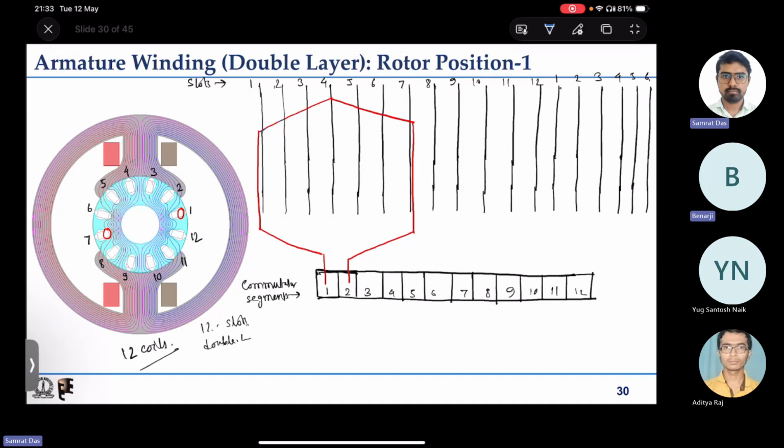So unless one is at the top and the other at the bottom, if you want to keep both on the top or both on the bottom, then the overhang will not have space. The length of overhang will be different, and that will keep increasing as you put more coils. For one coil it will be higher, and for the other coil it will be lower, which is not desired. Okay, sir. Got it. Thank you.